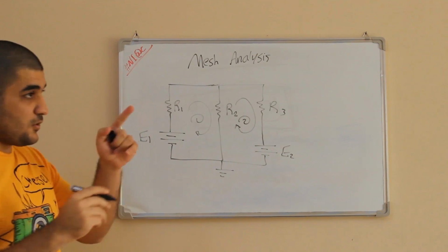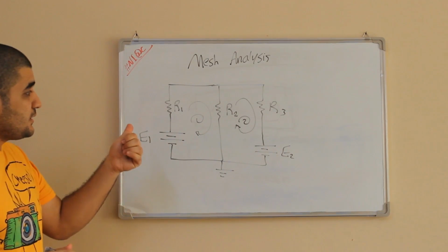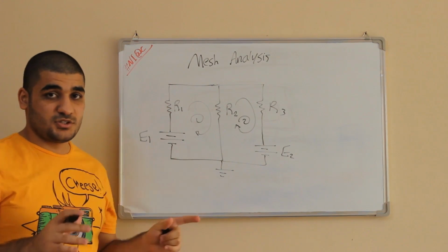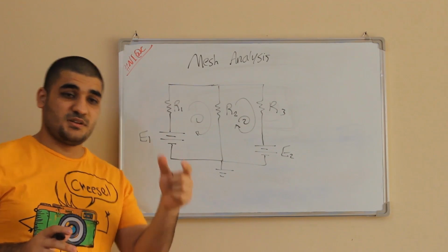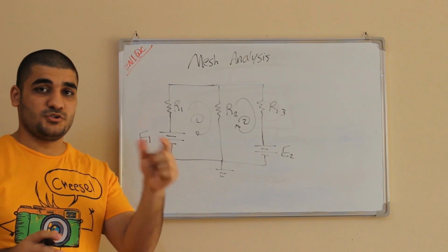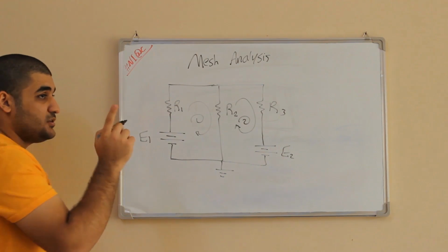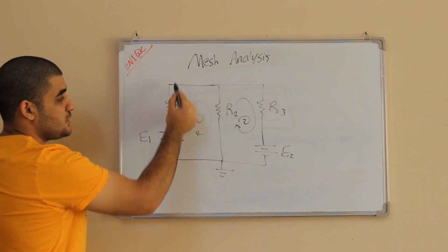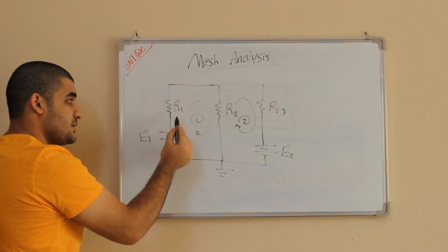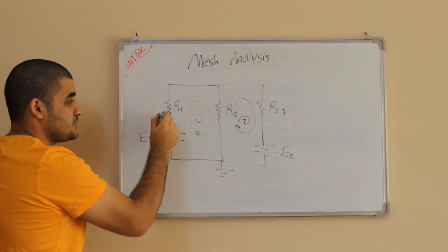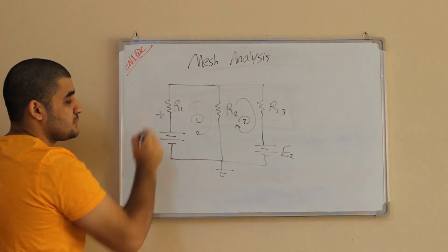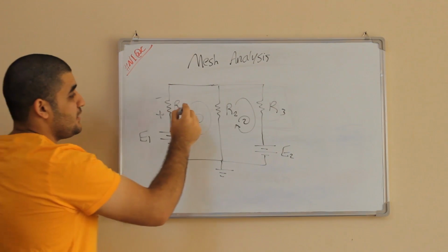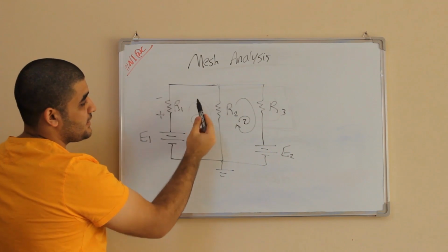circuit. That means on this resistor I have a voltage, but whether the voltage is positive or negative, you have to know where to put the signs. Depending on the current direction, look, it starts from here and goes upward, so whenever it enters the resistor element, you're gonna put plus. And the corresponding side is minus, okay? And continue in the direction of the arrow.